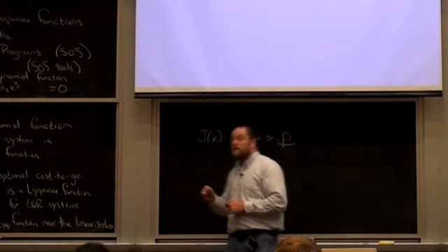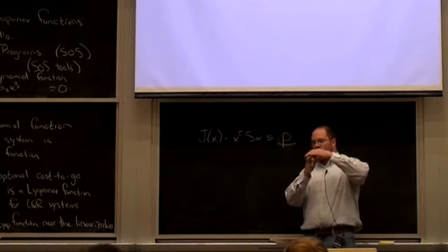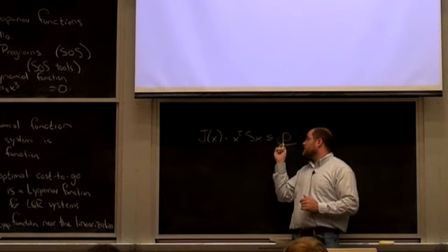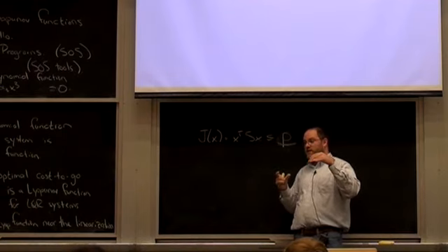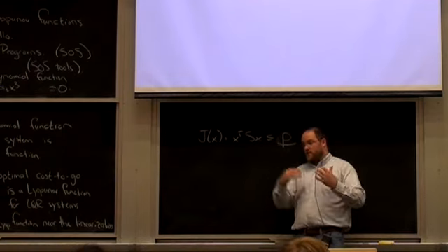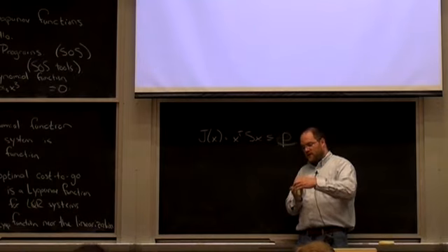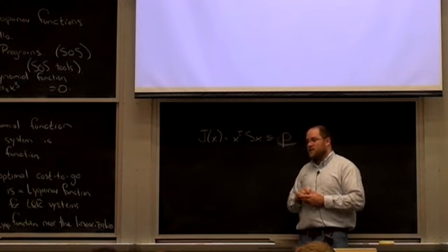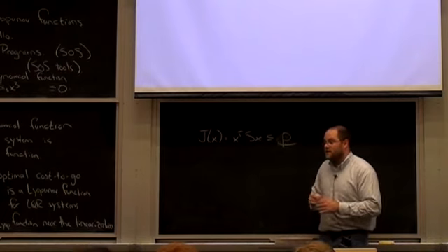That's exactly how we're going to verify it, okay? So there are two questions. There's a question of what shapes we're going to try to verify. The choice here is to verify contours of the cost to go function, right? I'm going to try to find the biggest contour of the cost to go function for the linear system. You're asking if I could choose a different shape based on the contours. What we've elected to do, and I think it's a tighter version maybe than what you're saying, but I could be wrong, is to find the biggest contour such that the next higher order terms of the linearization don't break the negative definiteness. This is just for purposes of choosing a shape.